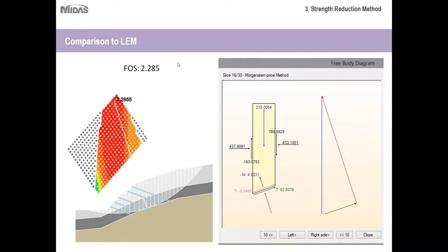Okay, then more about the limit equilibrium model. So this is what the results section looks like. Typically, once the analysis has been run, the program will isolate your minimum factor of safety. So this grid range here, these areas here in red anyway, represent the critical range, or the critical set of tangents where the minimum factor of safety is. So it's isolated the minimum factor of safety to this point here on the slope that corresponds to this tangent, and this is your critical failure surface with your minimum factor of safety.